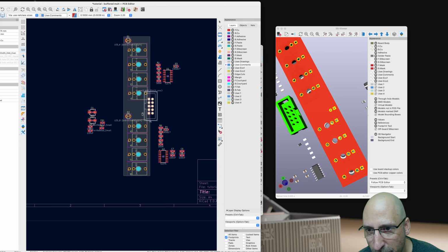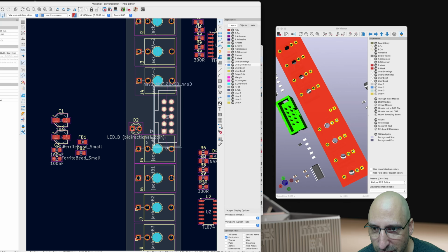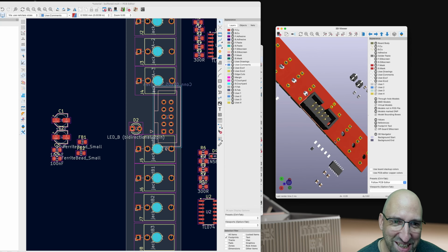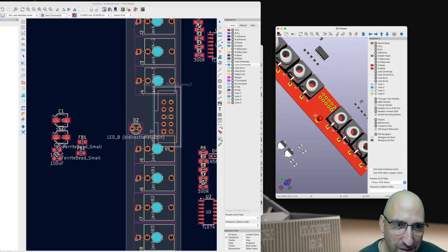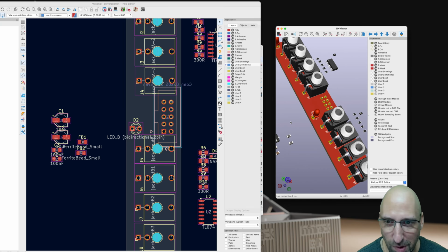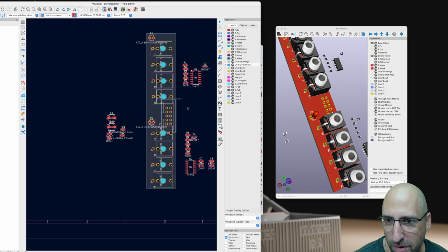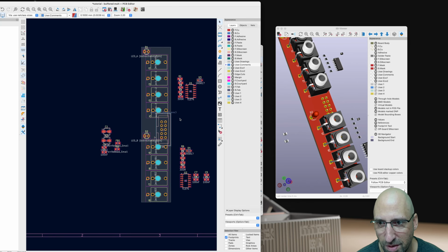So this could be one of those examples where we say, well, we're okay with it overlapping, even though it's complaining that it's hitting other components. We can physically see that we could solder that, right, without melting the output, and that's not actually colliding. So while it's warning us, we can just ignore the warning. Of course, we could also spend a bit of time and say, well, how else could we lay this out so that it isn't so constrained?